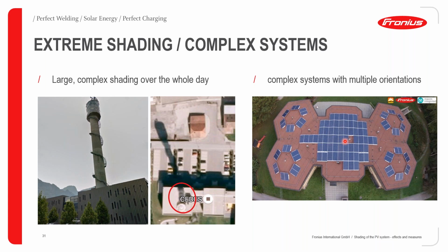And to the right here, we do have an installation that is quite complex, with the solar modules oriented in multiple directions. So this would be an ideal situation for you to use what are called smart modules. In the next slides, we will look at what a smart module is, and these are really becoming the norm for quite a number of installations. But for use where there is no potential of shading, then a conventional or traditional module with just a bypass diode is sufficient.